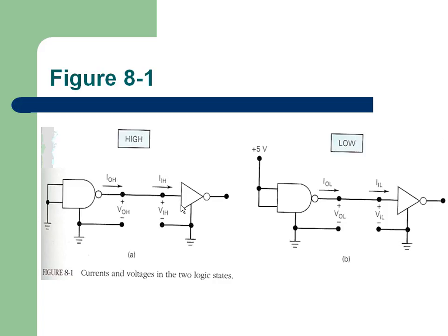But whatever it is, fan out, as we discussed yesterday, comes like this. Let us say this requirement is 1 milliampere, and the maximum this gate can drive is 10 milliampere, so fan out becomes 10. This requirement is 1 milliampere, whereas this gate has to drive 10 milliampere. At the most it can drive 10 milliampere, so 10 like this can be in parallel.